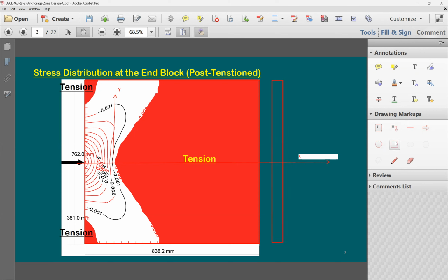At the beginning, the stress was only concentrated in here. This is where you have the bearing of this end block or the anchorage to the concrete. And then the stress goes from this over a small depth of the beam to uniform over the entire beam depth. This stress is in the x direction, compressive stresses. Also, this small block that I put a box around is compressive stresses in the x direction. But the stress distribution that you're looking at here is all in the y direction.